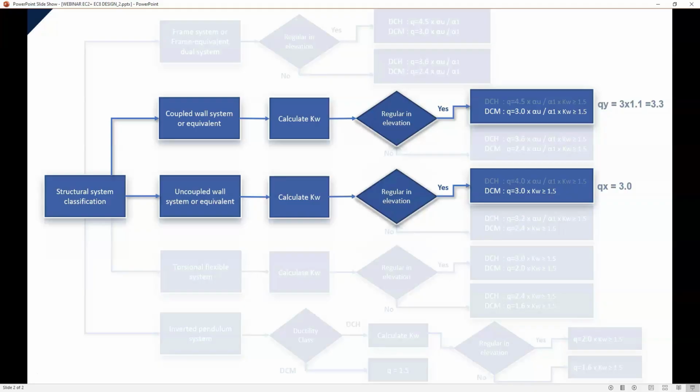We have seen many academic and professional examples where one of the checks performed is to calculate the base shear and separate it between the primary and secondary structures. This is a possibility, but from our perspective, it might not be the best way to do it, and I will explain why. For example, if this ratio is very close to 15% at the base, and we know that in wall or wall-equivalent dual structures where the walls have a very high predominance of stiffness, wall stiffness clearly decreases with height. It is common for structures near that 15% limit at the base to see the secondary element's contribution increase proportionally to the primary elements as we go up, assuming the geometric proportion of elements remains the same.